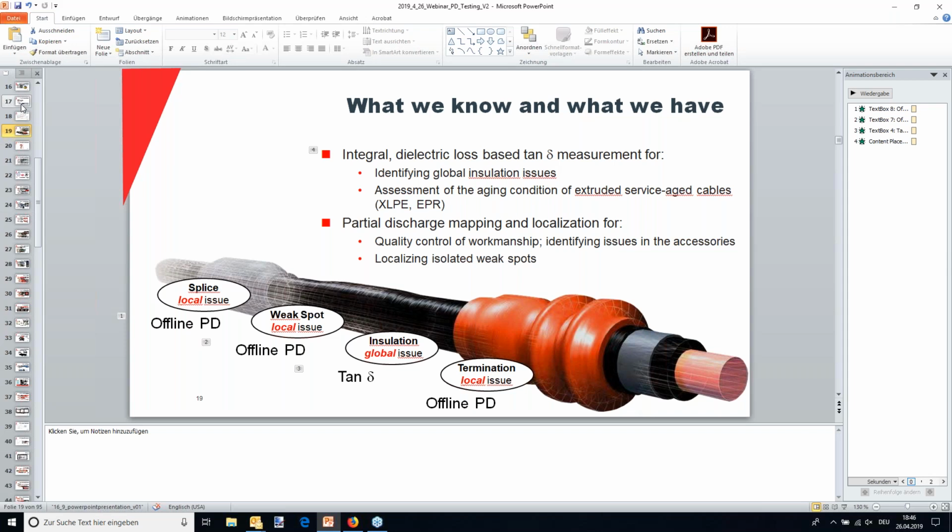Well, then the transformer creates a giant high capacitance cable because there's no way of isolating, so everything has to take the VLF voltage in those downtown network branches. But if you can isolate the cable specifically, also in URD and all of these applications, you should try to do that. And one more word on that, because Stephen said a practical question.